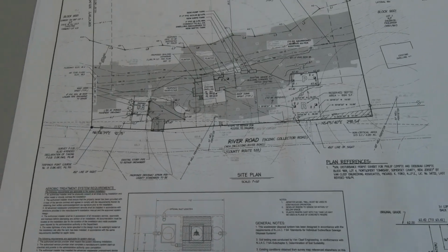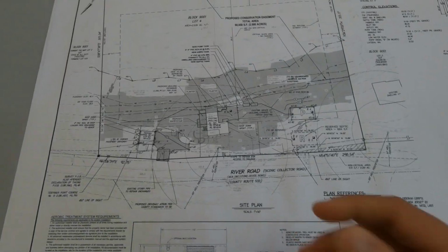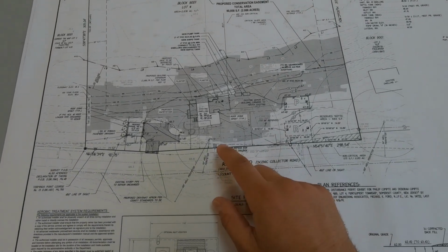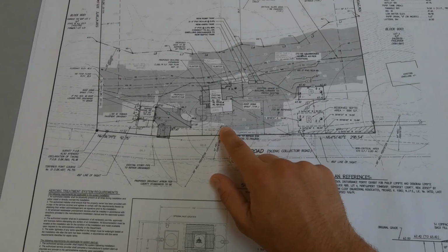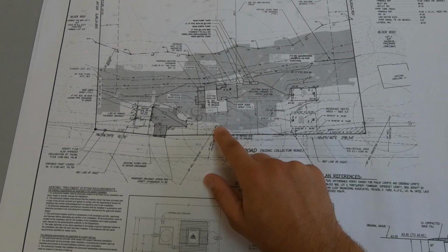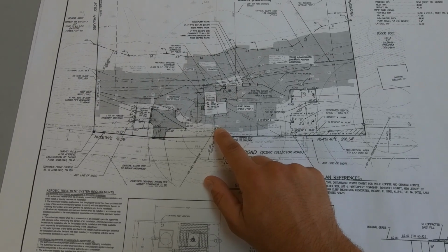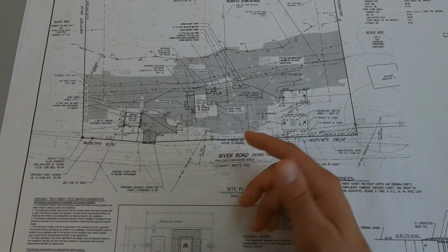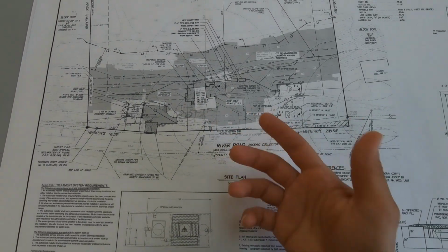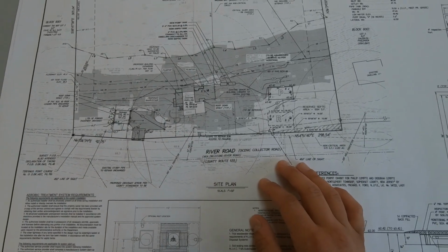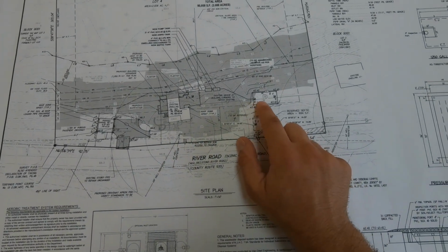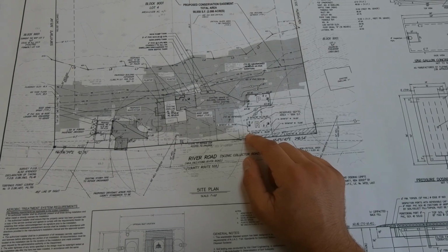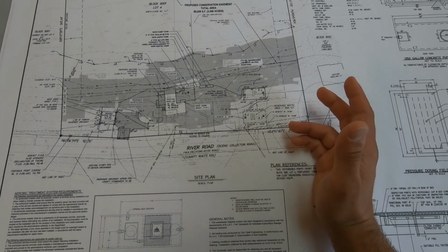Now, when you're designing this or when you're verifying the installation, you want to make sure that it is 50 feet from the well for the septic tank and pump tank, and the field should be 100 feet from the well. So these are some important details to know. Usually that's verified when the system is staked out, when the field is staked out.